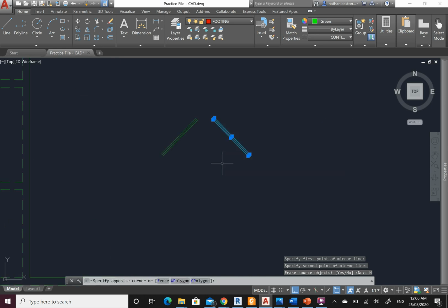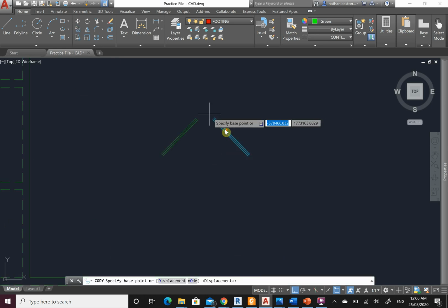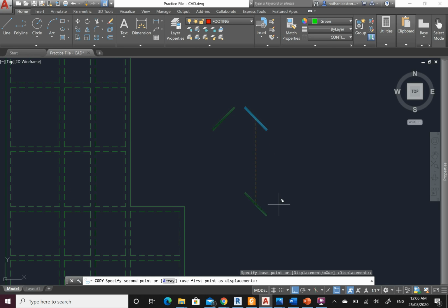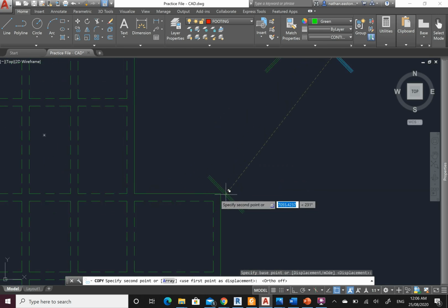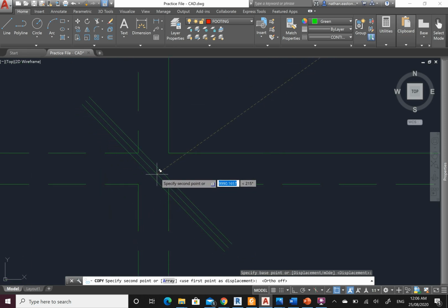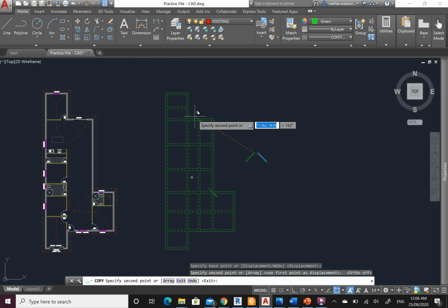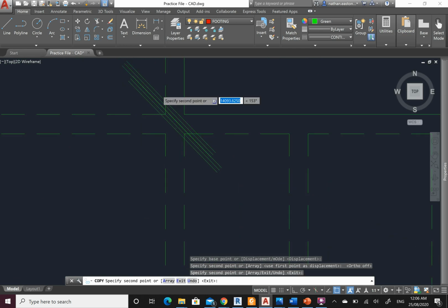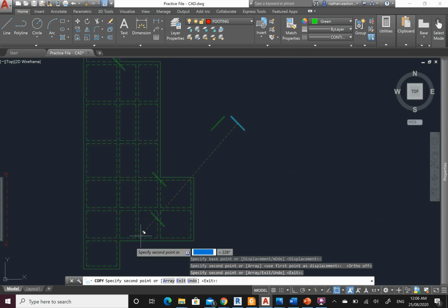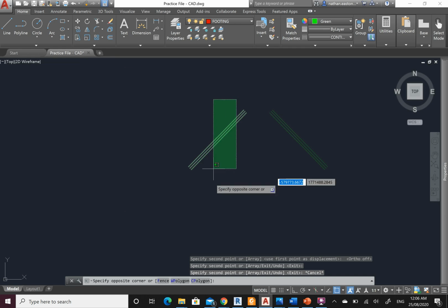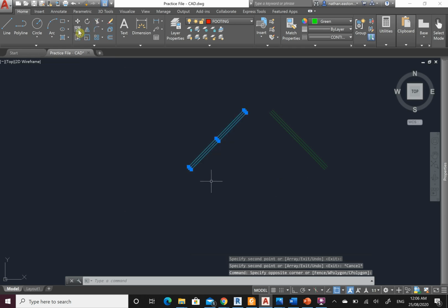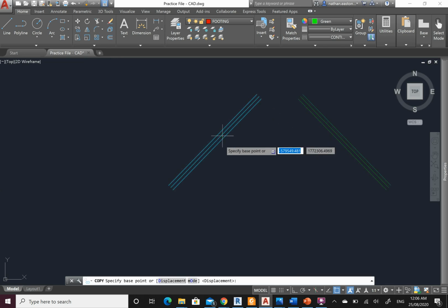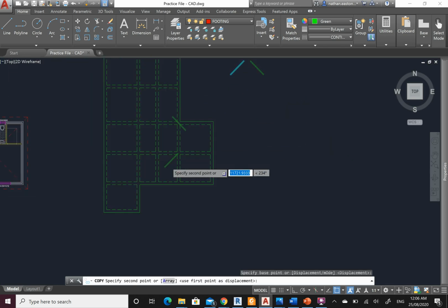So what do we do with them? Well, we copy them. And we're just going to place them. So I'm going to turn off my ortho. We're just going to place them here. So this beam comes in and then goes, nah, I'm not coming inside anymore, I'm going this way. So this here is a reentrant corner. This here is a reentrant corner. I have another one here, but it has to be these. So the whole point of steel, when it comes to cracking of concrete, is the steel has to cut through where the crack's going to happen.